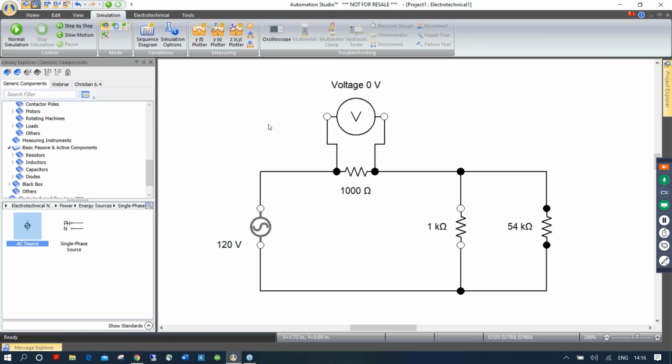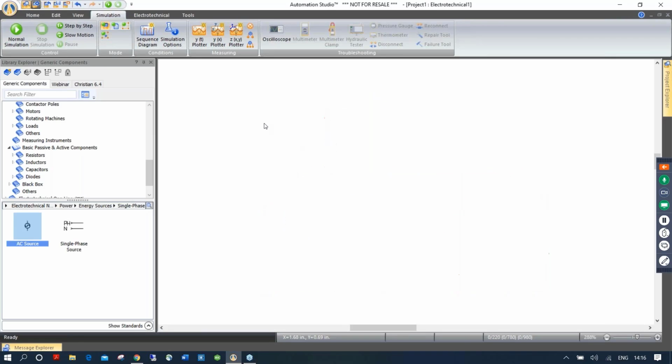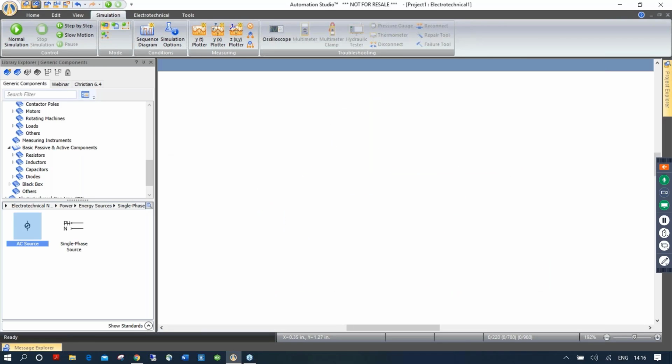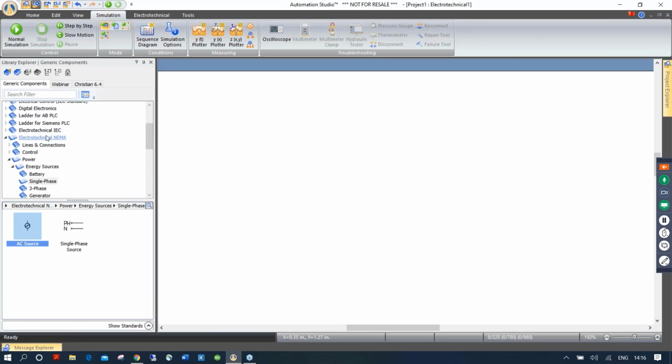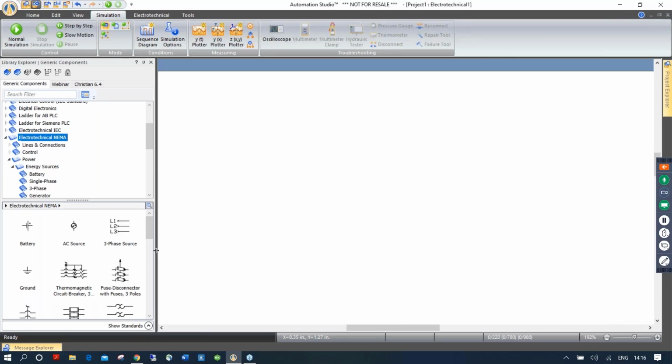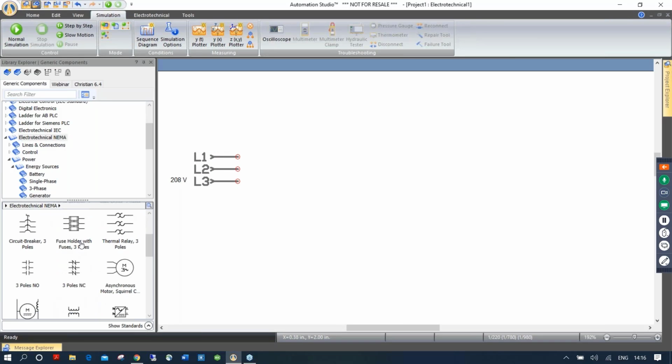And now what I would like to do is I'm going to build a three-phase forward motor control. Okay? So I'm just going to erase all that and actually come out here in my library. And I know that everything I need, again, it's at the main source of my library, so I won't need to browse to the library. So I can take a source. I'm going to put, let's say, a circuit breaker right here.